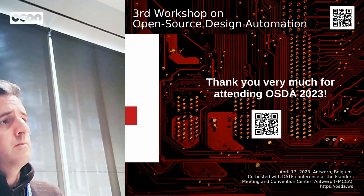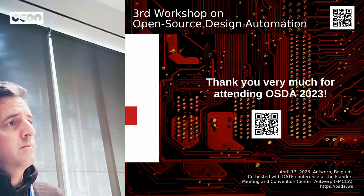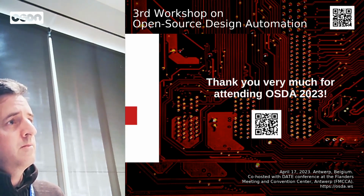The fact that you have to wait for so long every time you make the slightest change to your design. Now, I understand that it's a difficult problem in general, but I have a lot of structural information available to me in the source code that is being completely thrown away in trying to resynthesize and re-PNR from scratch every time. I have modular structure, etc., where it seems to me that it ought to be feasible to do an incremental change in one part of the FPGA without touching the rest of the FPGA, and hopefully the design cycle will greatly speed up there.